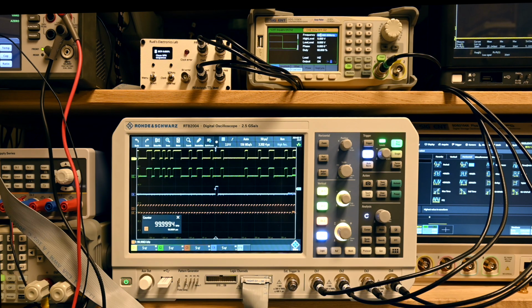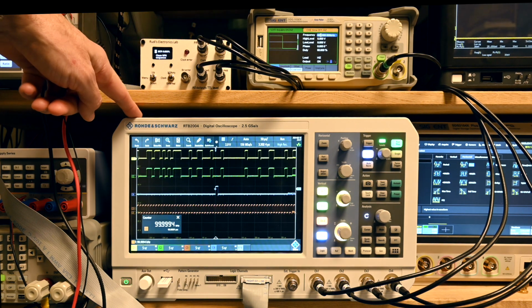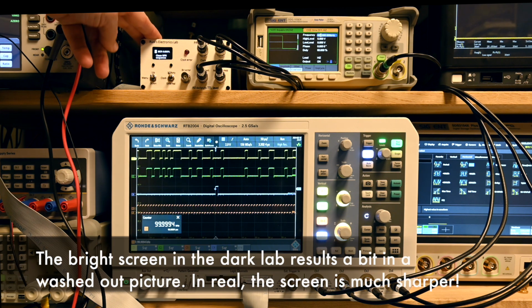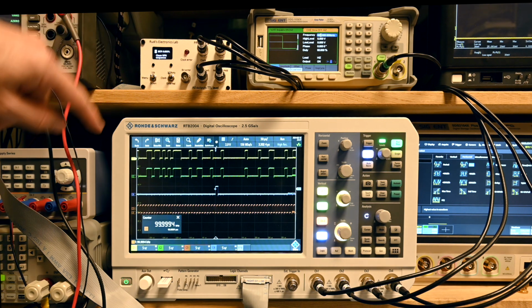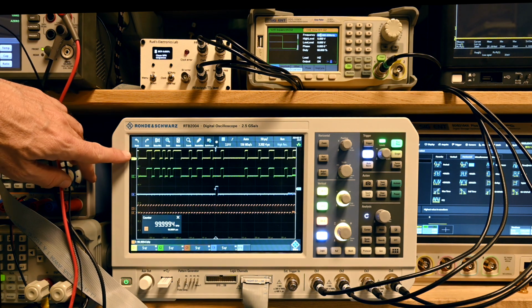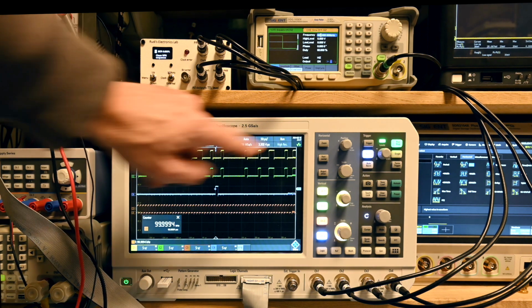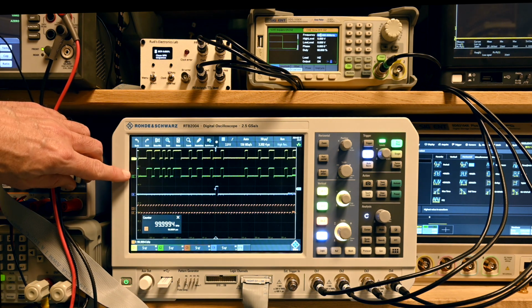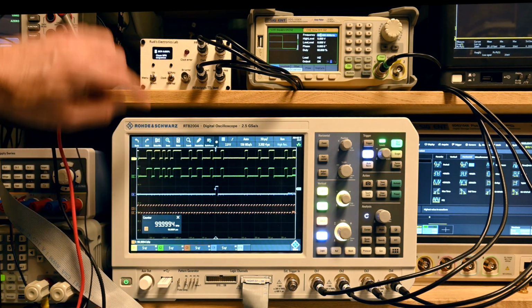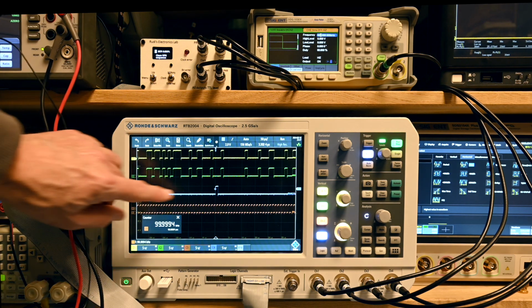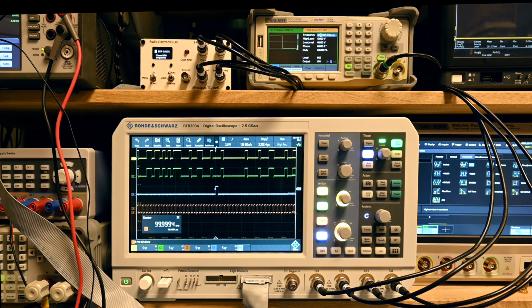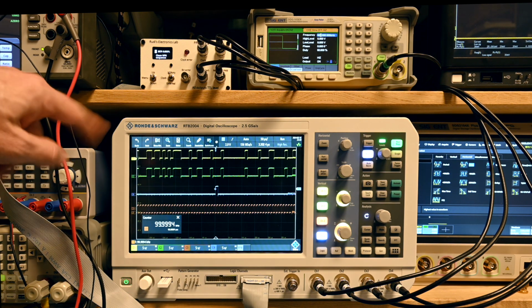Okay, it's already getting a little bit late, but I still would like to do some field experiments and see how the signals out of our PN9 generator look on the oscilloscope. So let's just start by looking at the output signal when we start in a basic scenario with a clean output, and it's pretty straightforward. On channel C1 we see the PN9 code, the 511-bit PN9 code coming out of the device. On channel 2 we see the modified signal, but since this modified signal is also the clean signal, it's the same thing. And on C4 we see the frame start. So this is every time the 511-bit frame of pseudo-random bits repeats itself.